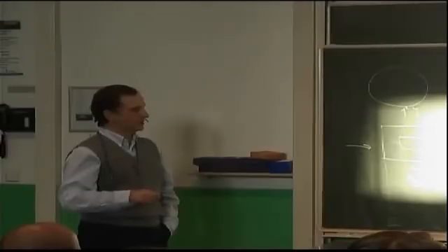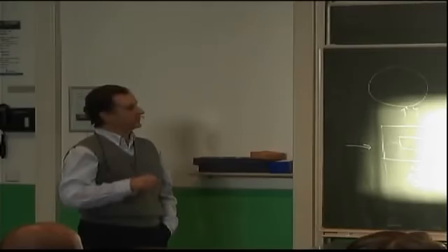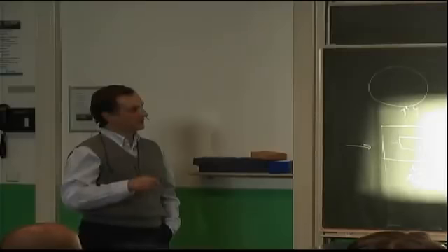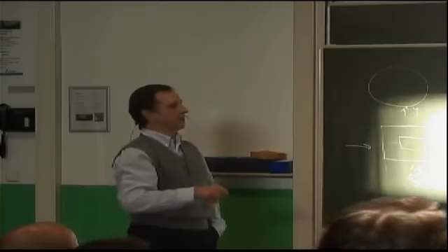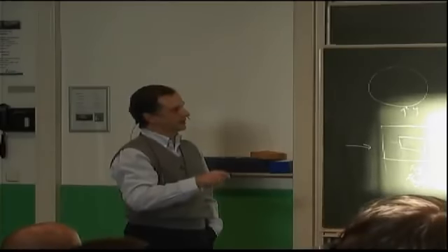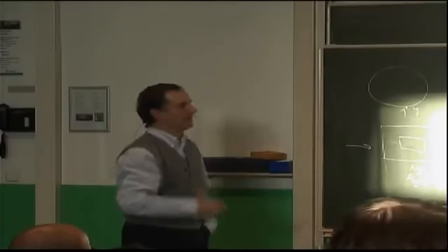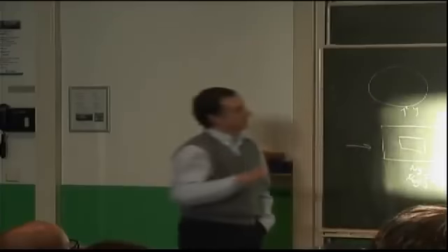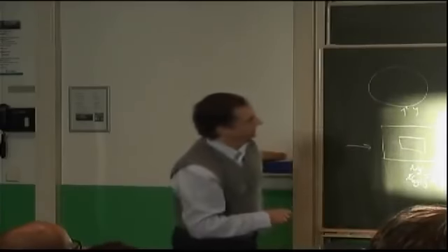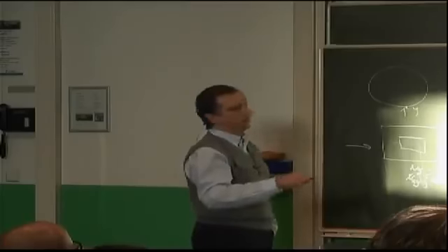Now, you can take my word or you can substitute and prove it that if you use this nx, ny, and nxy, you satisfy exactly the equilibrium equations and all the boundary conditions. In fact, the way I came up with that is I started with the nxy, substituted in the equilibrium equations, found nx and ny, then substituted in the boundary conditions, and then I fixed all my constants that I didn't know at the time. So these expressions satisfy all the equations that we need to satisfy. But the H_mn coefficients are unknown, and those are the ones that we will determine by energy minimization.